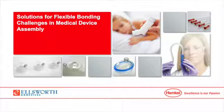So imagine a plaque of adhesive cured completely, and that is what is typically submitted for the full ISO 10993 biocompatibility. There have been some instances with certain adhesive chemistries where that cannot be easily done, having cured films made. So in that case, most of those adhesives are tested on control specimens, in most cases a polycarbonate lap shear that's a medical device grade that's known to not contribute to biocompatibility. So hopefully that answers that question.